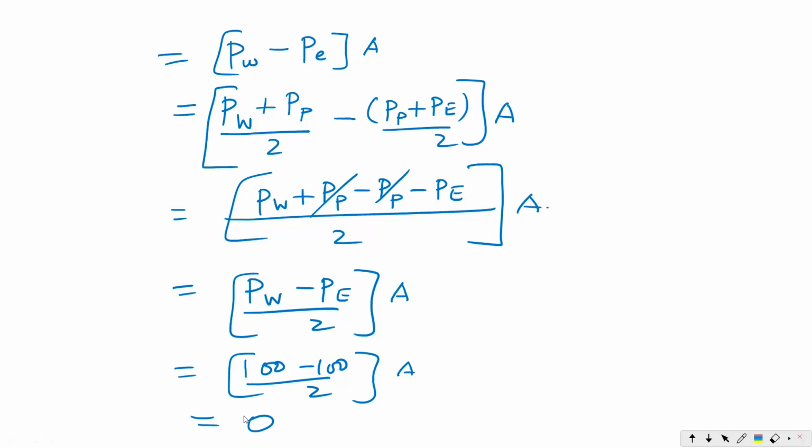But in the real time physics, the flow will happen either from left to right or right to left. The flow will happen because of pressure gradient. Since in this method we are not able to capture the real physics, we are trying to explore why. That may be because we are storing both the scalar variable and the vector variables in the same cell center. If it is going to be staggered, then we can overcome this problem.